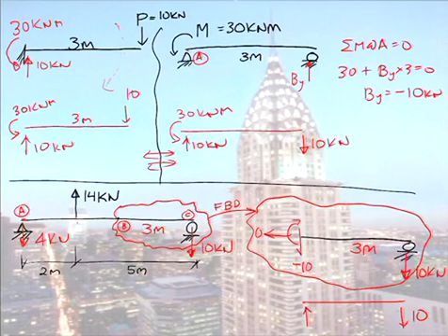And have a guess what my moment is equal to. Yep. Okay, so that 10 is pushing it clockwise, so we have a 30 here, kilonewton meters. This time round, this 10 is a shear force, this 30 is an internal moment. But look again just at the system of forces, and that system of forces is identical. So the point I'm trying to make is calculating internal forces is no harder than calculating reactions.